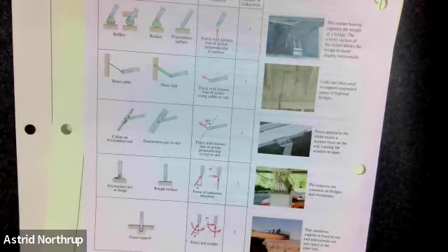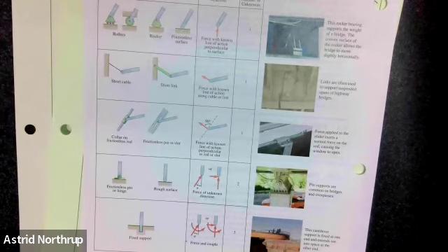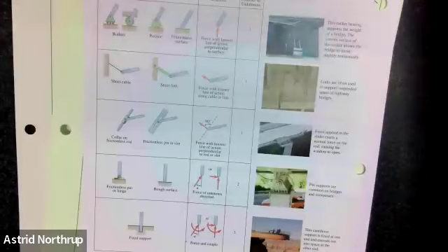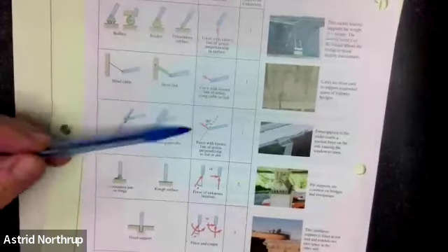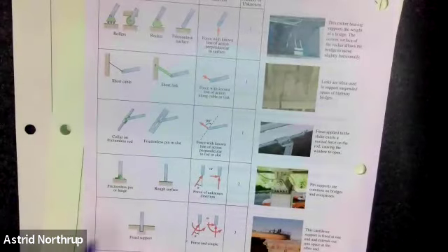If you think about it, a roller, like this chair, how handy we have furniture, I can push on it with almost nothing in this direction, I can move, because it will not bear a force in the x direction. The only kind of force it bears is straight down. Now, if I push on it too hard, it's going to tip. But that has to do with some other issues as well. But so these will tell you what kind of reactive forces you draw in your free body diagram.